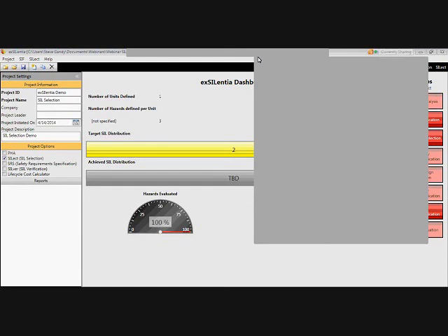So most of the time your final elements will be static. They won't be moving. So cycle test data doesn't apply in those instances, because number one, they're continuously moving. Number two, they don't have the environmental conditions, because these tests are done in labs. And number three, you don't have product moving through them. So you could have dirty product moving through them that would have different problems for the particular final element device. And you don't check for stiction, which is something that happens. So that's very important to recognize.